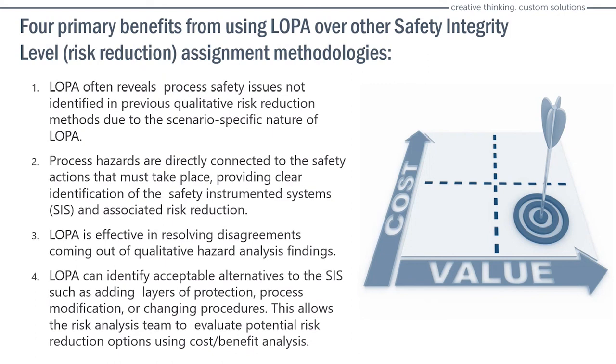LOPA is effective in resolving disagreements coming out of qualitative hazard analysis findings. We've been in some PHAs where there's a large disagreement between what engineering thinks is an acceptable PFD and what an operator or management thinks is an acceptable PFD. And so, you know, let's go investigate it. Let's go look at what that PFD is.